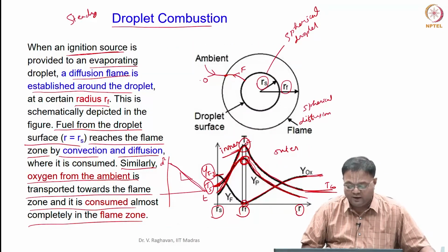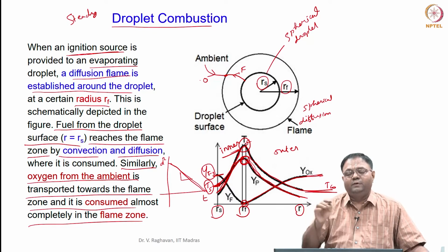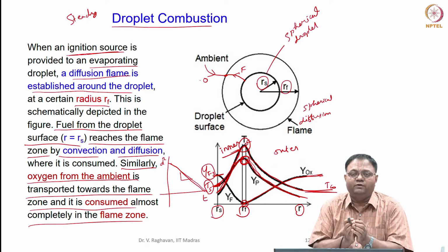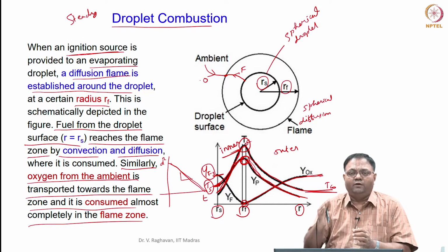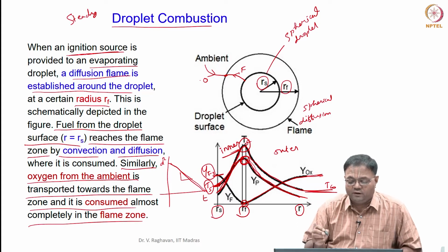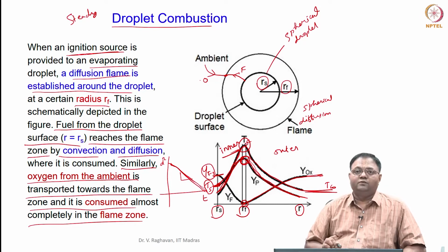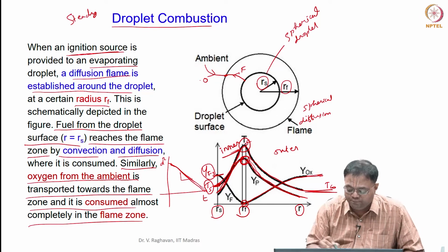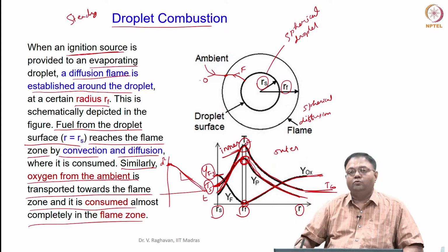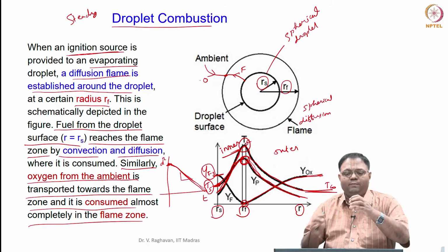We are assuming a one-dimensional spherical flame adhering to the droplet surface at a distance, say R_F, from the center of the droplet. As the droplet regresses, the steady evaporation range is formed. The diameter of the droplet is going to decrease to zero, and then the flame will reduce to zero. Till then some vapors will be there.